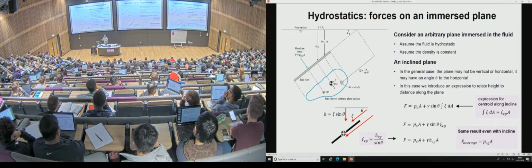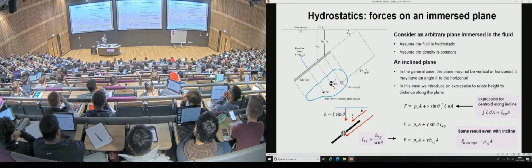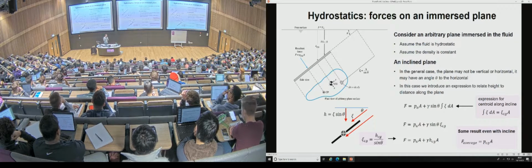So in a triangle you could start from the base, in a circle arguably you could start from the radius. But in an arbitrary shape, rather than start from one of the extremities, which may not make sense, you generally start from the center of gravity, which you can always get for an arbitrary shape, and then you do your analysis for second moment of area from that point.